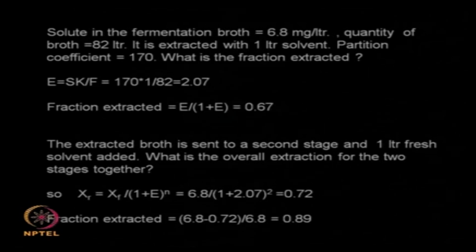So if you are really interested in extracting all your solute, it could be a protein of interest or it could be an antibiotic of interest, you may resort to several stage operation so that you recover as completely as possible. So this is a cross flow type of design. We will later on look at counter current flow type of design.